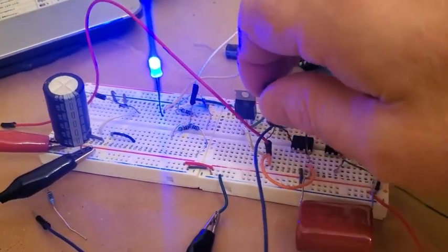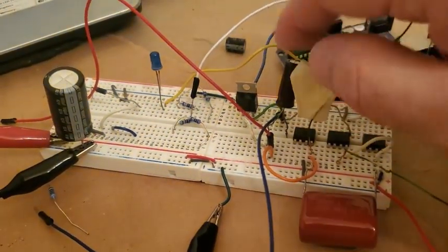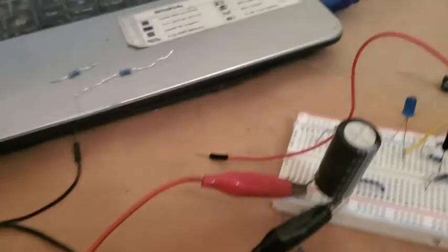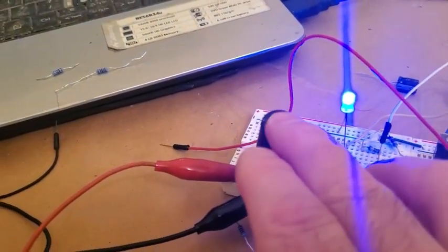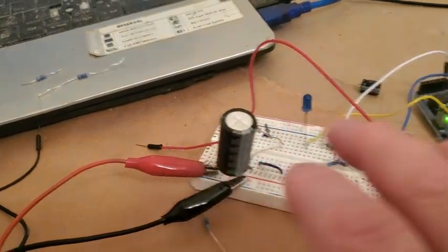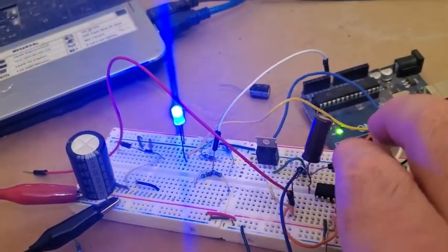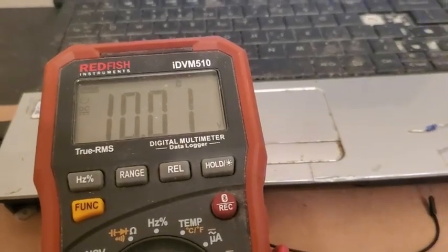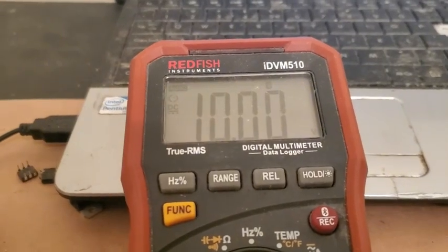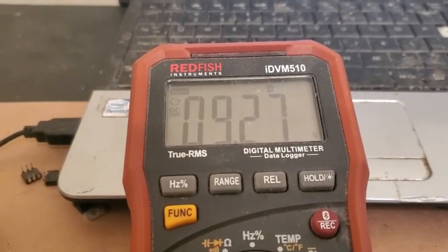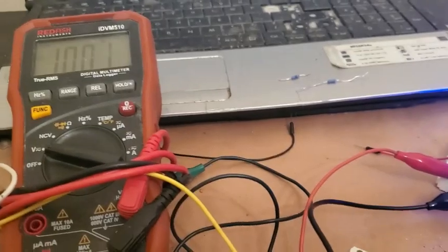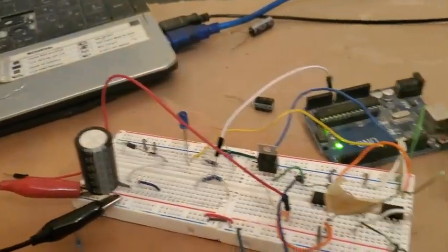Oh, I'm going to leave it in for a minute. The diode's out, one leg of this is out. I don't want to destroy the thing. Power back on. If the thing's unloaded, what does this cap go to? We saw last time it discharged from 10 to 9.33 when we were putting power into here. So now we're going to do it again with it not loaded. 9.27. So isn't that interesting?